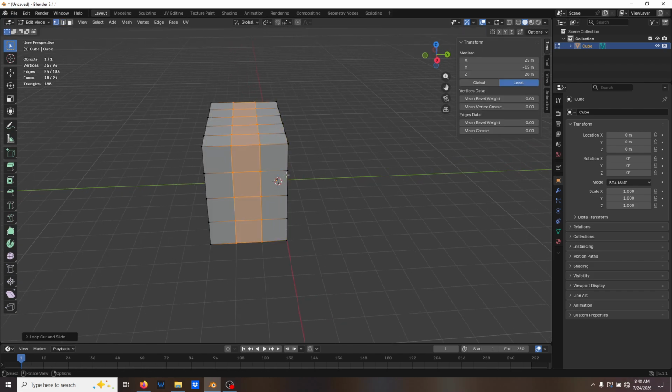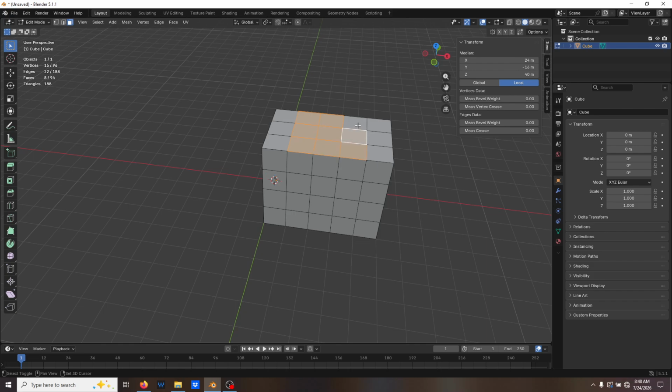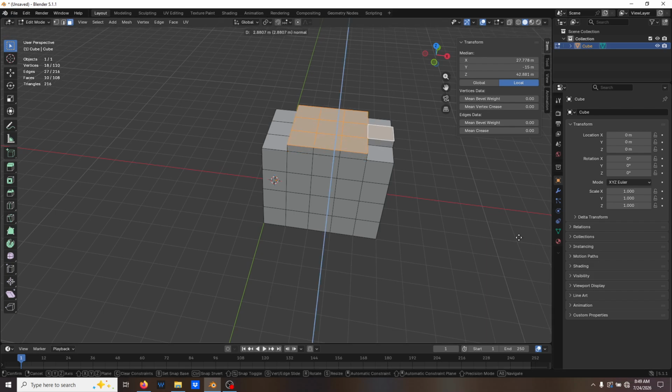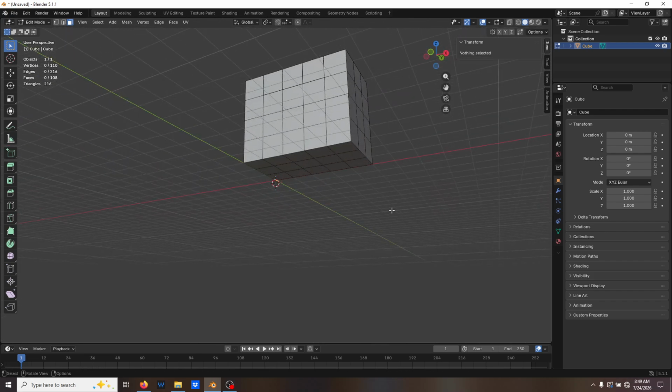Okay, so now with this one, I can also take advantage of some of those doubled vertices. And what I'm going to do this time is go into face select mode, and I'm just going to extrude some of these faces, and then I'll delete the edges that go in there, because otherwise I kind of have to go in and fill all of them by themselves. So I'm going to grab these, and I'm going to say extrude. I'm just going to say -10, right? Okay, there we go. All right, so then I'm going to grab these ones down here too.